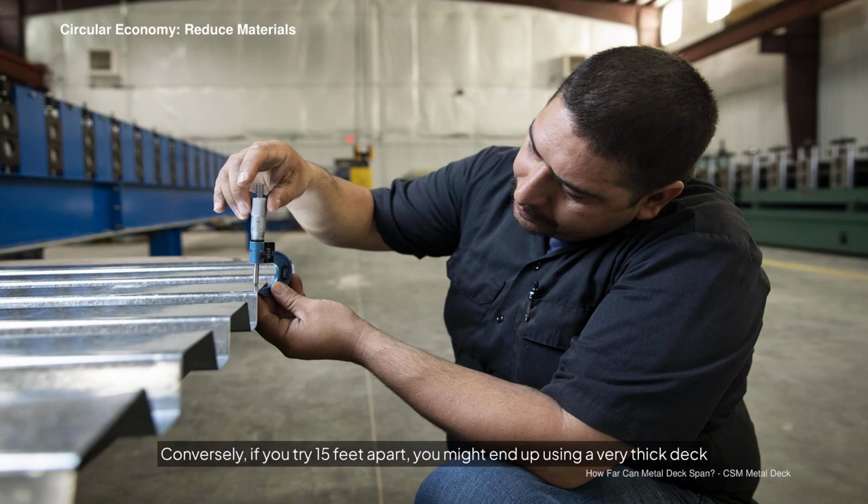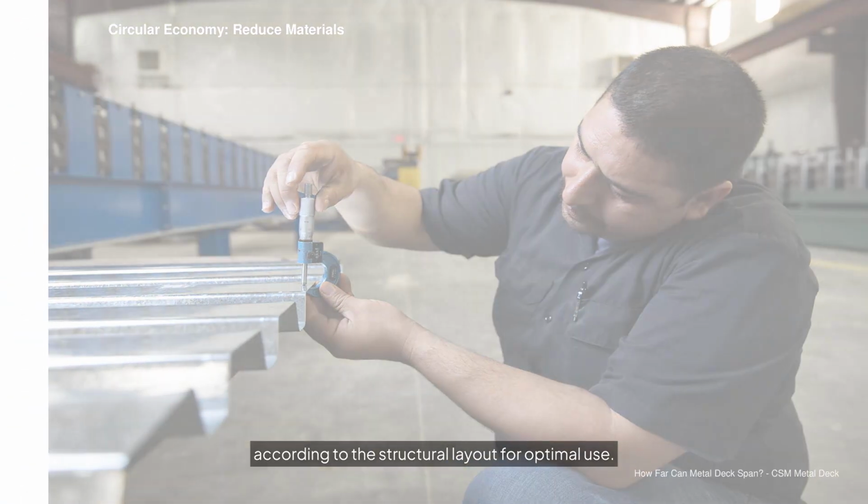Conversely, if you try 15 feet apart, you might end up using a very thick deck or adding intermediate supports, again extra material. Either scenario means more material usage than needed. The optimal is to push materials just to their efficient limit, but not beyond. From a reduction standpoint, we need to match the efficient span of materials according to the structural layout for optimal use.